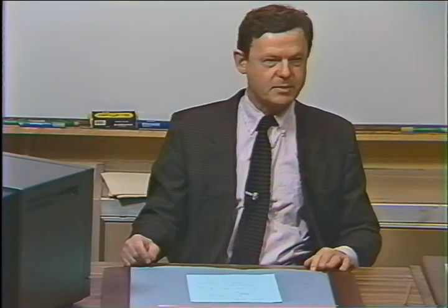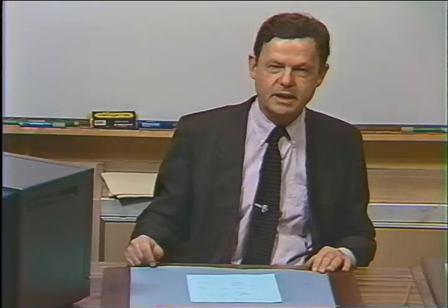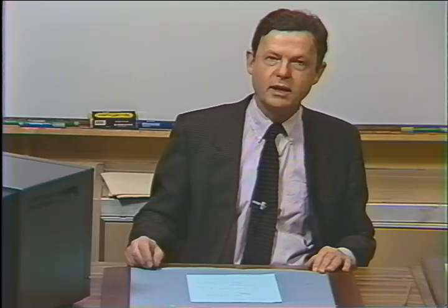We started to talk about the stress tensor, which defines the forces which are locally transmitted in a material. For doing that, we take a little area element, dA, in the material, and that element had the normal n. With that configuration, the force transmitted through that area element would be dF. If you divide this force by the area, dF divided by dA, that would be the traction. And we would have to take the limit of a very small area element.